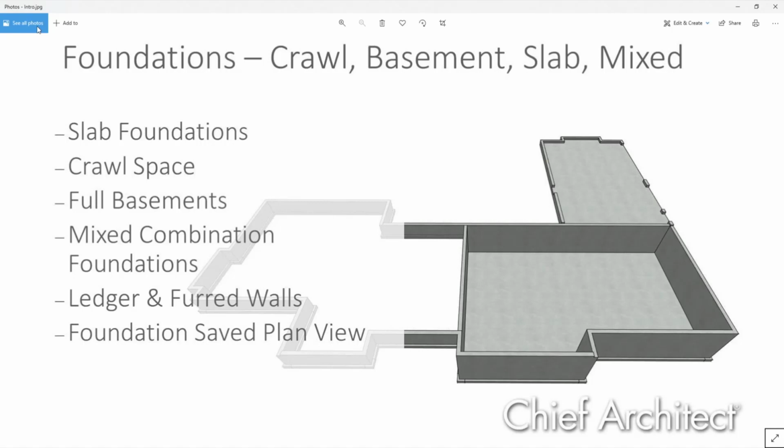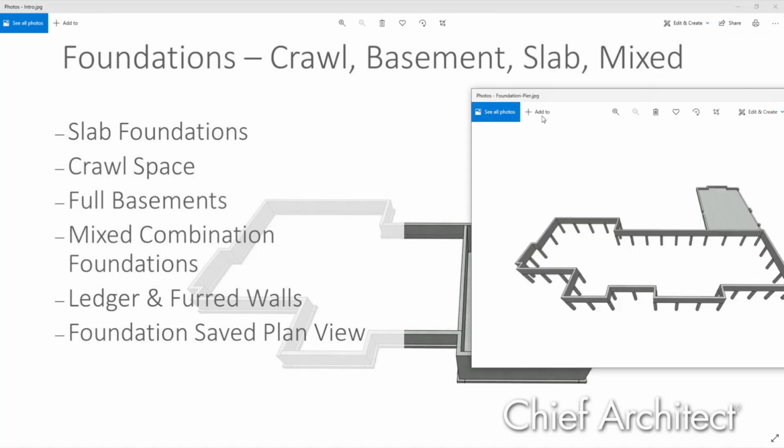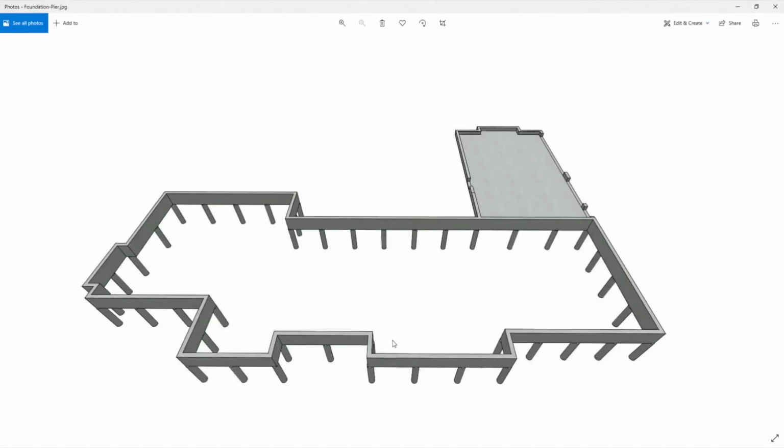So when you build your foundations, there's an option to build it on pier. Do you use that option, Derek? I don't. Okay. So when you build your foundation on pier, here's a variation of the foundation I built on pier, where I just used the default settings. When you build it, all of those objects can be manipulated. So you could pull the wall over, or copy and paste those piers. It comes in at the right elevation.